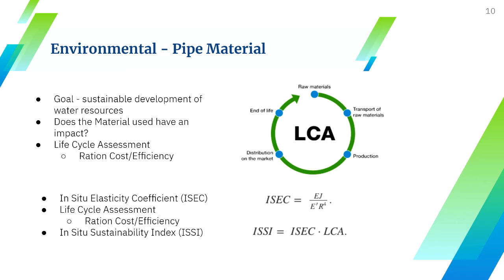Stiffness is defined by the rigidity modulus depending on the material characteristics through its elastic modulus E and the size of the pipe through the inertial moments I and J. The first depends on the tube thickness alone, the second on the ratio between the thickness and diameter of the pipe.